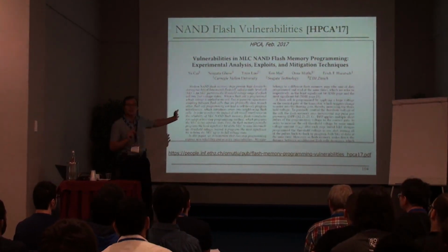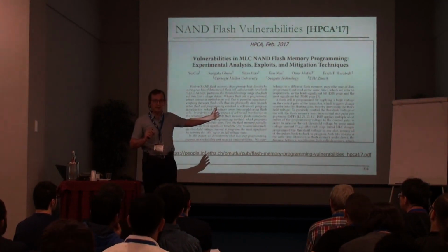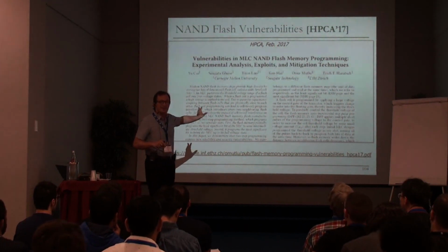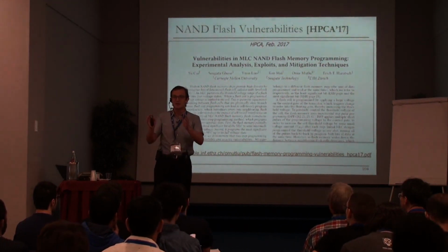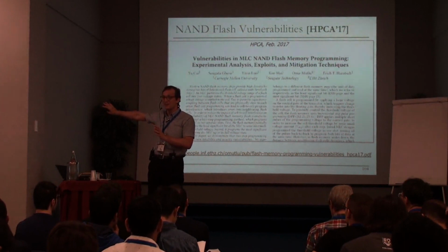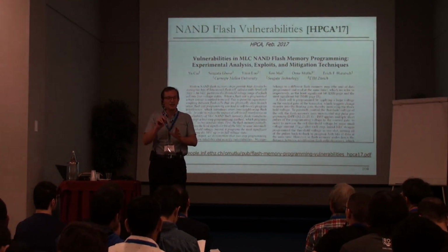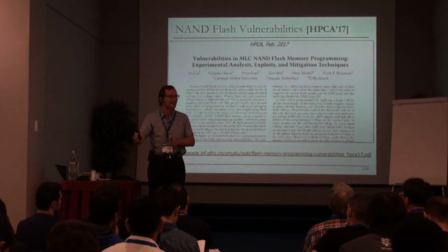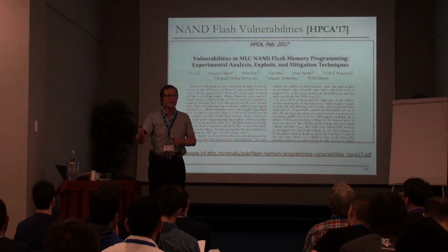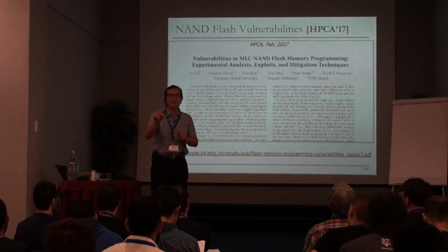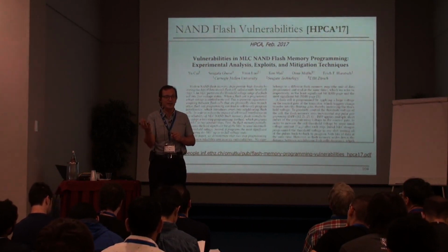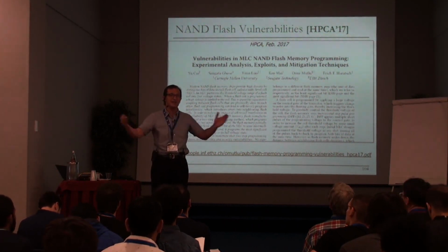It turns out read disturb issue exists in flash, and we found that this could also be a security vulnerability. I believe it's a security vulnerability, but it's very hard to exploit because flash memory sits very far away from the processor. In order to be able to impact a bit over there, you need to go through layers and layers of the software stack, layers and layers of the firmware stack, which includes the flash translation layer. And if you want to induce errors predictably at some locations, even when you know the device behavior is very unreliable and you get predictable errors over there, it is not that easy.